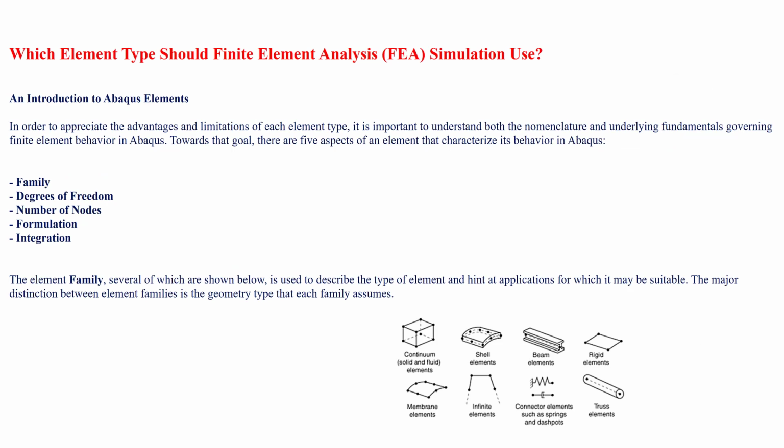Yeah, so as I said before, I wanted to explain more about these element types. So which element type should a finite element analysis simulation use, right? If I consider Abaqus, there are different types of elements with respect to the family, degrees of freedom, number of nodes, formulations and integration.